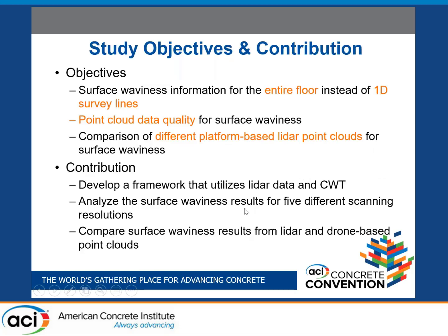Our objectives were to see whether we can characterize the entire floor using this laser scan data instead of using one-dimensional survey lines. We also wanted to look at the required data quality for the point clouds, because it may be computationally very difficult to process laser scan data if it's a very large project.